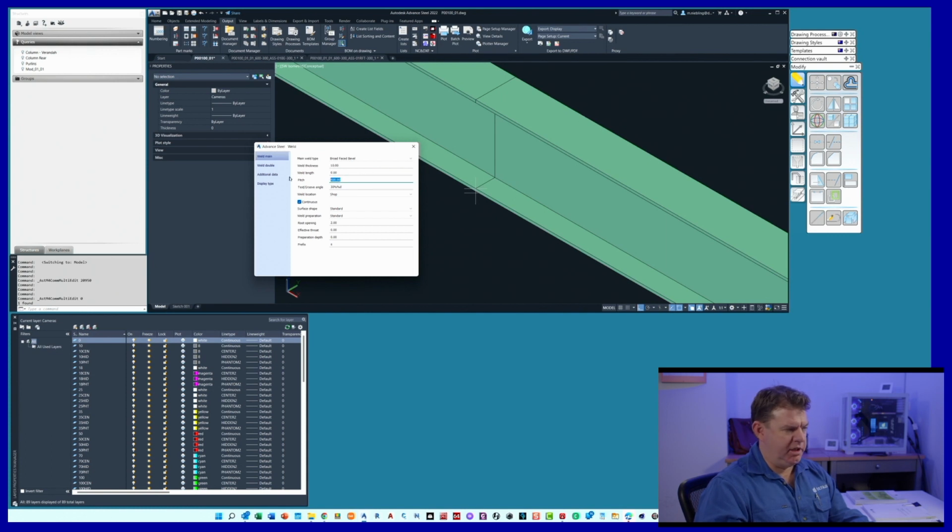Let's get rid of some of that stitch welding information. The text for the groove is, we'll make it 45 just to show a different value. It's a shop weld. Let's show some other information here. We will put in that it's a convex, and the weld preparation here for a groove weld. So we'll go groove weld, and it's a machine finish. A root gap of 2.